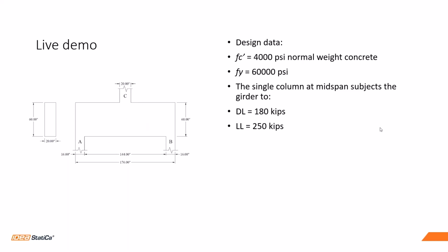So as a result, these beams can be subject to larger shear forces and bending moments in comparison to conventional beams. So again, how will you address this type of problem? Well, there are guides, and from the ACI code, you will use Strut-and-Tie. So let me show you how you can use IDEA StatiCa Detail for this type of situations.